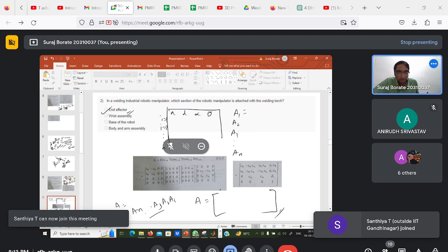And what is this homogeneous transform? How is it related to the forward kinematics? If you see the 3 entries of the homogeneous transformation matrix that will come up, besides the bottom row 0 0 0 1, there will be some 3 entries. What will that be? That is nothing but the position of the end effector, as a function of all these a, d, alpha, theta for all the links. So this is the forward kinematics. This is how you get the forward kinematics.